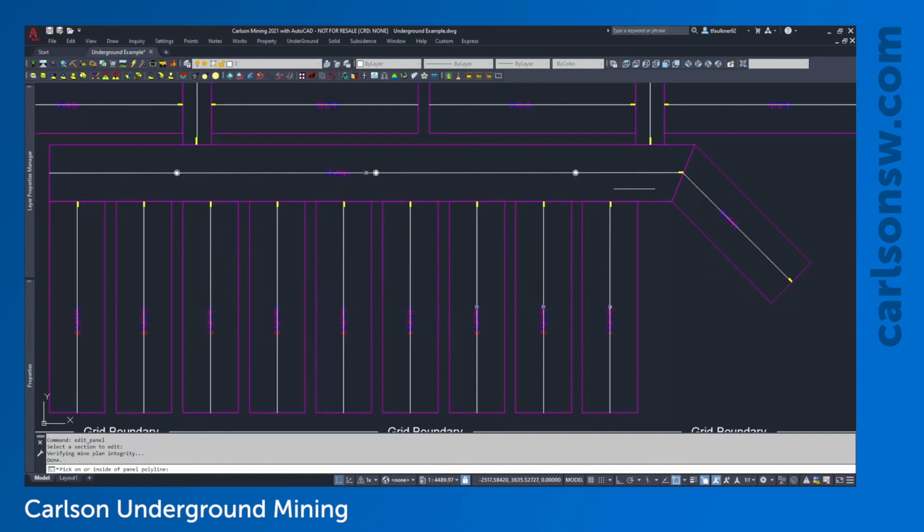So what I can do here is just click inside the panel that needs to be mined before this production panel. So I'm going to click inside this main panel, and notice when I do it, I'm going to click on this side of that pinpoint. Once I click, it tells me that it added the panel main 2 beginning through the first pinpoint to the precedence rule.